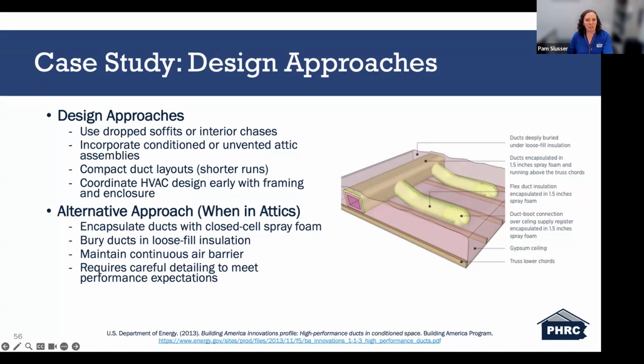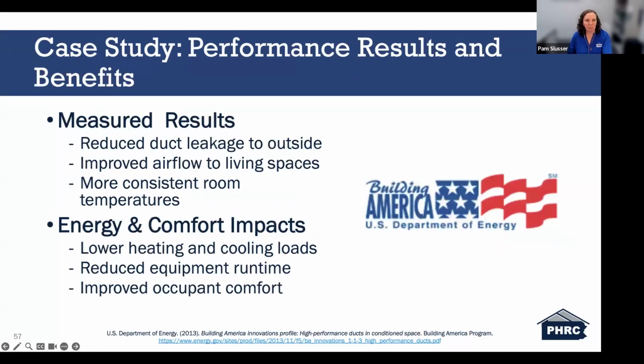And just as important as coordination, HVAC design needs to be considered early alongside framing and enclosure design to make these approaches feasible. So when ducts must remain in the attic spaces, and you have no other alternative, approaches can be used, such as encapsulating the ducts with spray foam or burying them in insulation, but these require careful detailing to perform correctly. So just be careful with it.